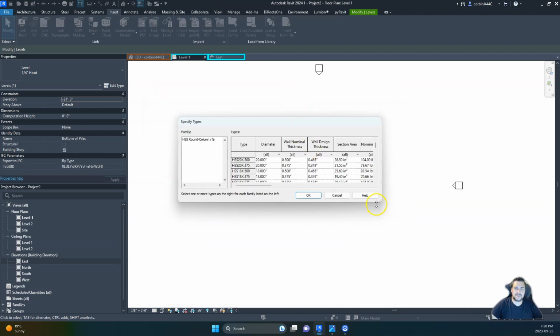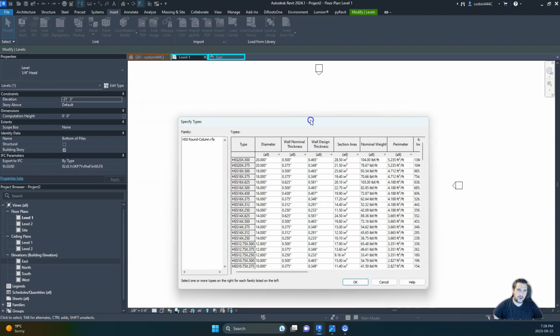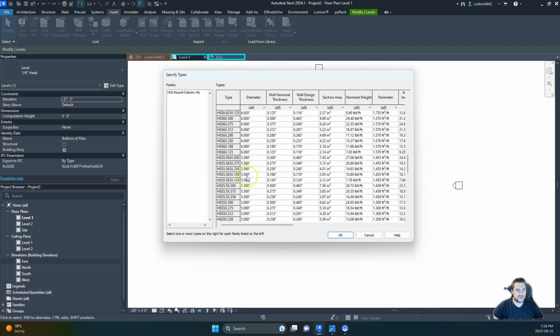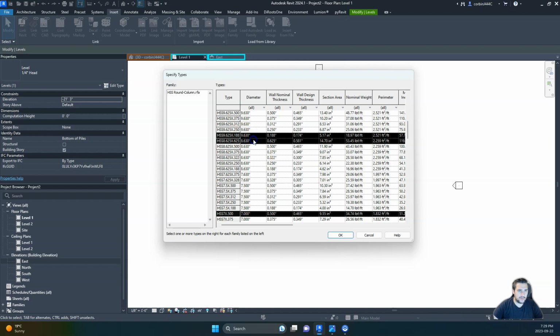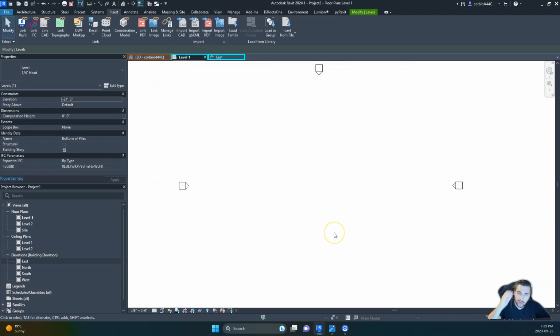It's going to ask us what sizes we want to bring in. Generally, most columns are around 5.5 or 6 inches. So we can bring in a 5.5 by 1/2 or 5.5 by 5/8. They use really thick columns for dock structures. It just helps longevity. They often will use 6s, 7s, or 8s, and this is very much dependent on the depth of the dock structure.